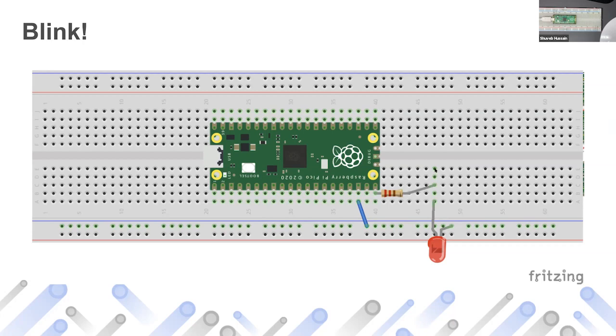And then, like I told you, these columns are connected, correct? So I'm connecting a resistor in this column here, which means this resistor then connects to the LED. And then the LED is connected to ground. This particular pin number, pin number 18, is ground, which means negative power. So that's connected here. This essentially gives negative to the LED, and positive we are connecting through the GPIO, which we can control using our program, right?